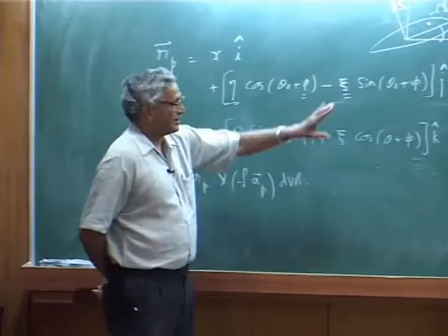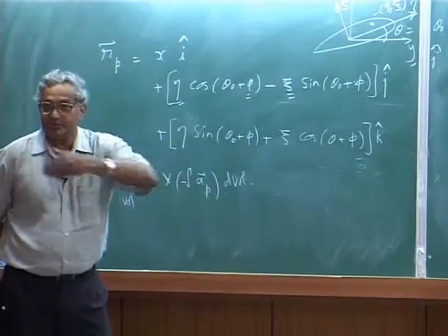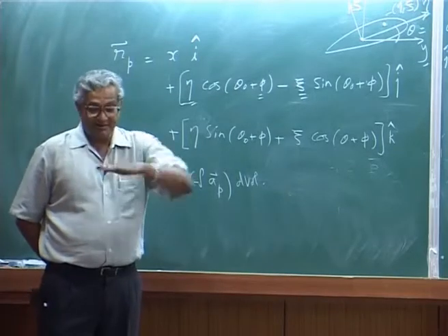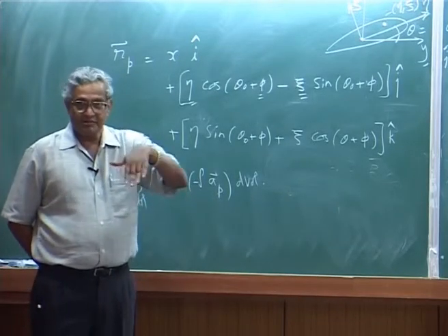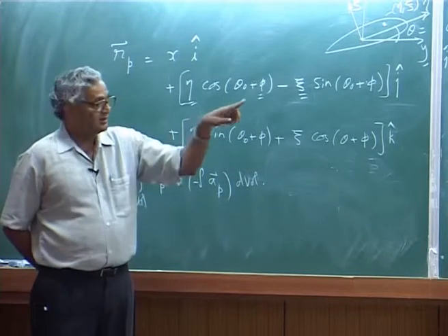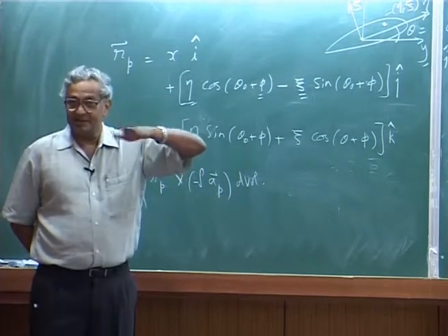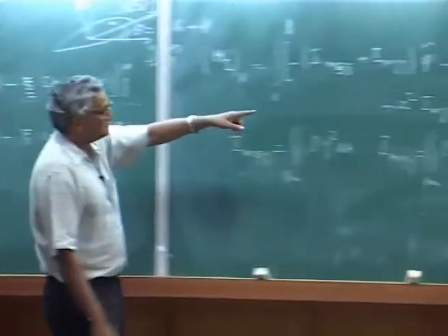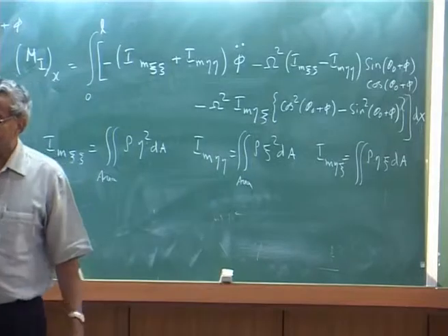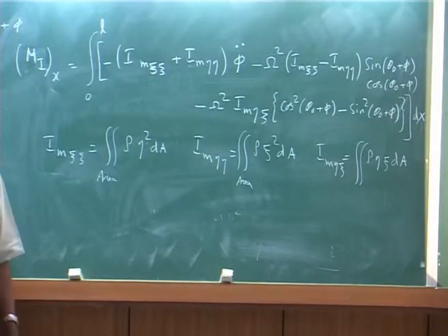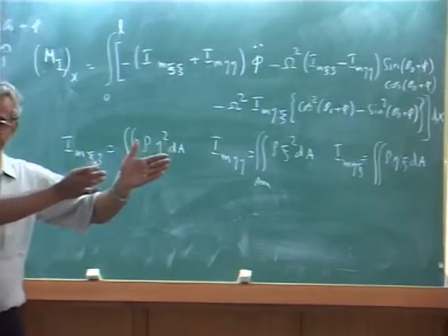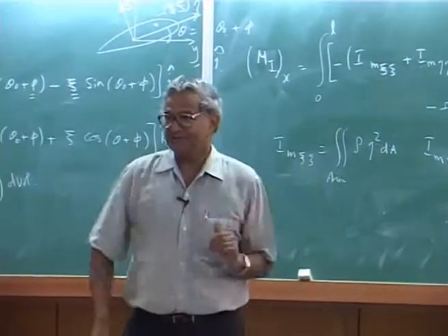Now what you can do is combine this aerodynamic moment. But when you say it is an oscillating aerofoil, because phi is not constant, it is time varying, phi is a function of time, that means you are talking about a moment on the aerofoil which is a function of time. Okay, so it immediately goes to unsteady aerodynamics.